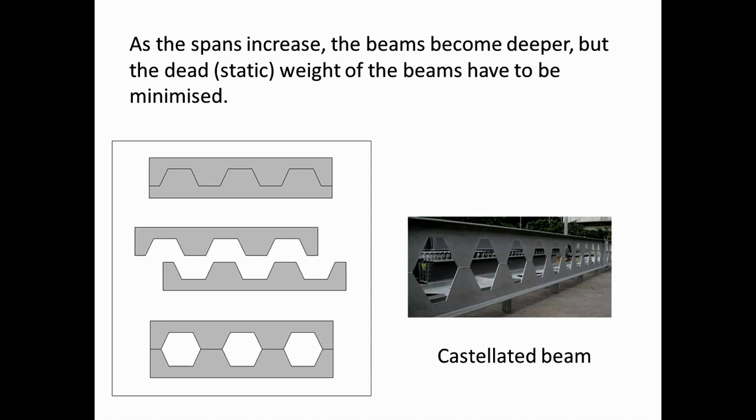Now, as I said to you, I think in the lecture on structural physics, the key to spanning is that the longer the span, the deeper the section of the beam. Whether it's an I-beam or any other type of beam, there is a strict relationship between the length and the deep section. You remember loading that simple timber section and how you turn it around to resist loads. That's what's going on here.